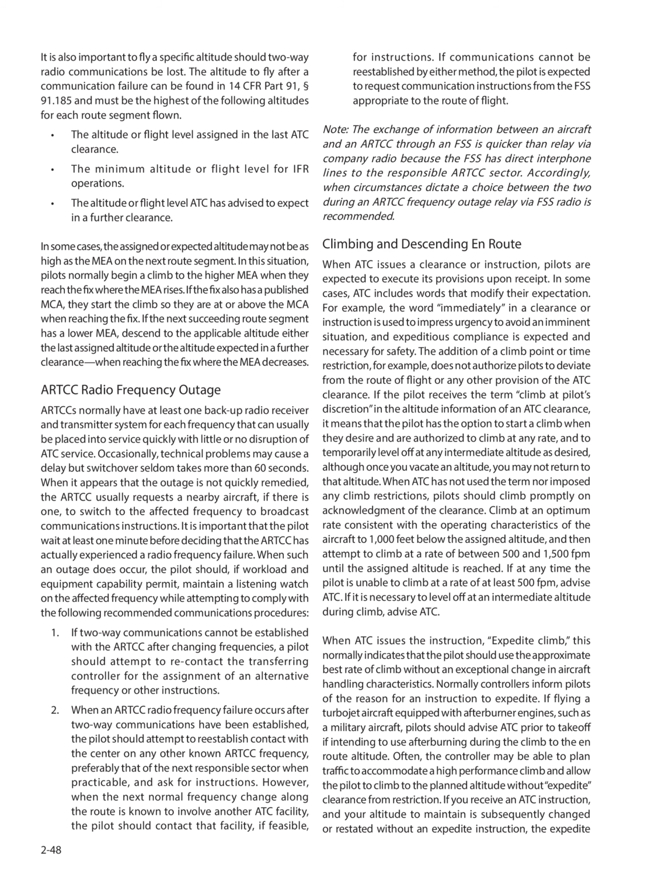ARC radio frequency outage. ARCs normally have at least one backup radio receiver and transmitter system for each frequency that can usually be placed into service quickly with little or no disruption of ATC service. Occasionally, technical problems may cause a delay, but switchover seldom takes more than 60 seconds. When it appears that the outage is not quickly remedied, the ARC usually requests a nearby aircraft, if there is one, to switch to the affected frequency to broadcast communications instructions.